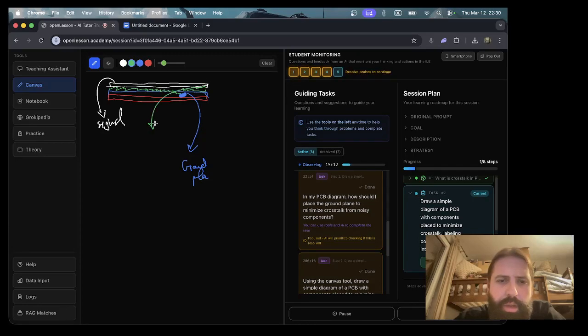They cannot touch each other, right? At least this gives us one thing, which is that the magnetic fields generated by the signal paths and the ones generated by the blue layer kind of cancel each other, so there's less noise.